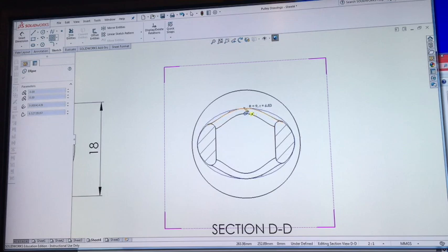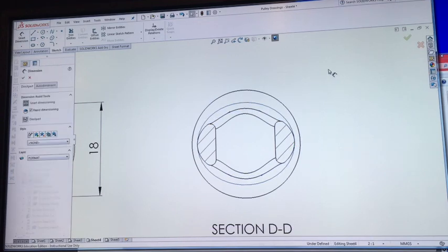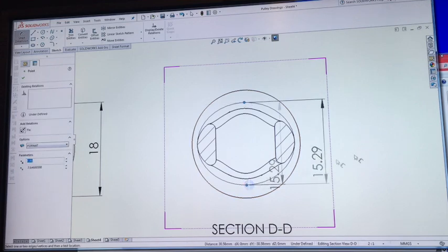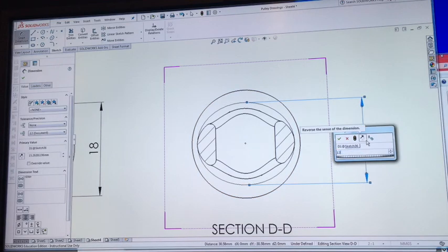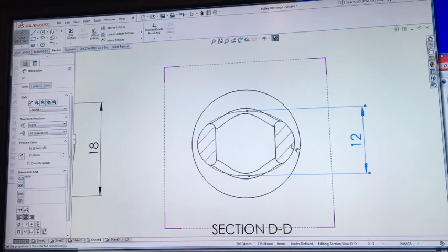Now when you're doing your ellipse, be careful not to snap it to this edge. You can see the dimensions next to my cursor. They're saying a radius of 9 and a radius of 6.5, which is not correct. It should be 6. That edge is not the ellipse shape. Instead, just drag it out a little bit further, and then when you add a dimension, you can manually put in 12 and it'll resize that ellipse.